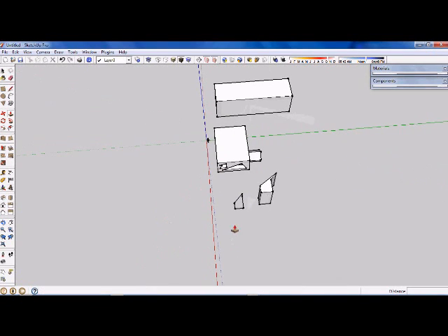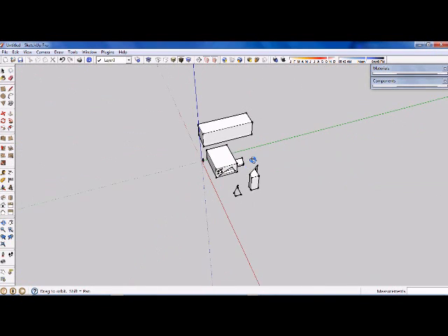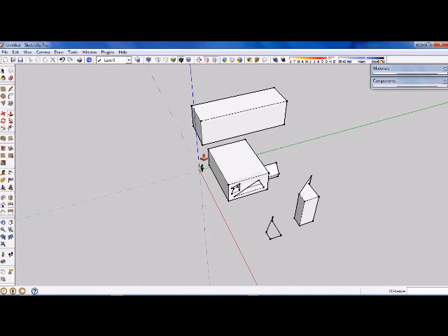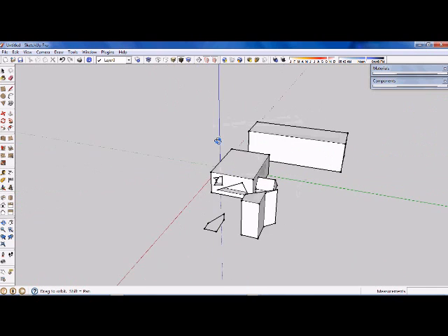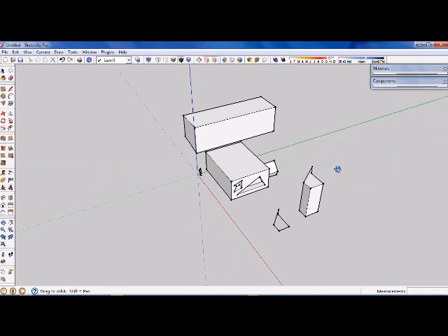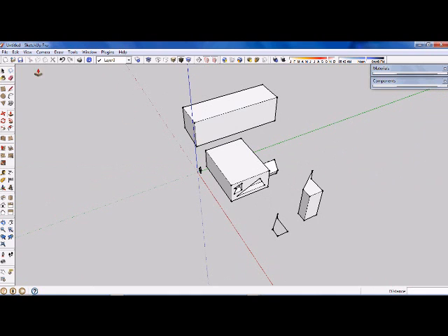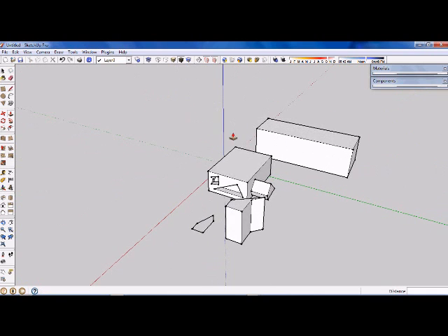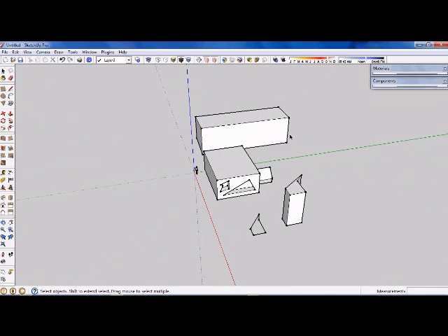Let's even show you how you can erase items and select different items inside SketchUp. To do that, we'll use that to be able to create a bit of a clean sheet. One of the easiest ways you're going to be able to find to delete, or first of all select, groups of geometry that are all connected together is to just go up and pick up your select pointer tool, this tool up through here. Now this just enables you to select things.